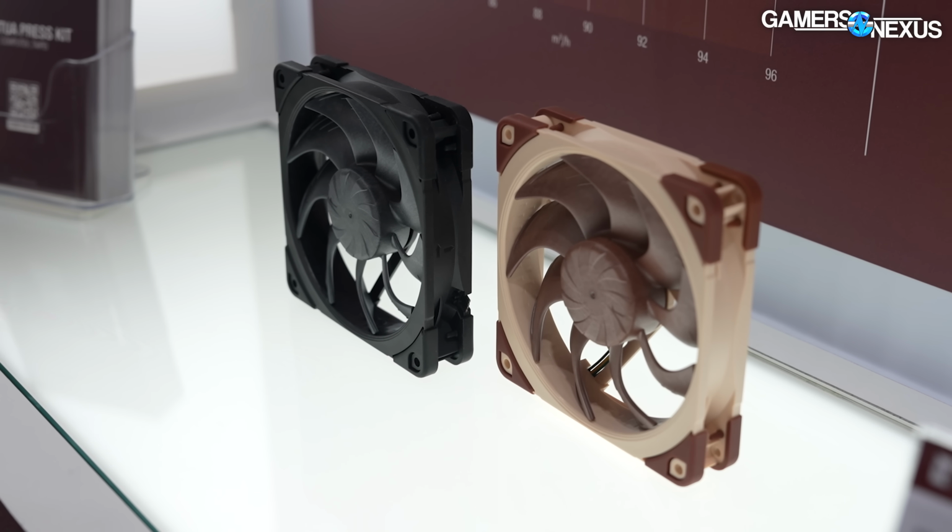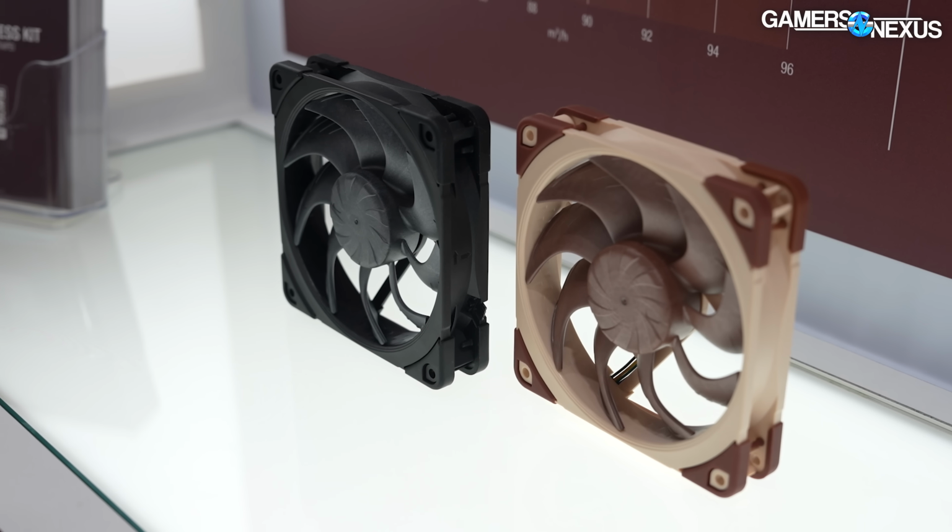But usually this is something that, when you start a fan design project, would rarely change in later stages of the development. This is something that's usually locked very early, and then you're playing with more minute details to do the fine tuning. So if you got the blade angle wrong by more than 1 degree in your initial design proposal, then you wasted a lot of time if you have to change.